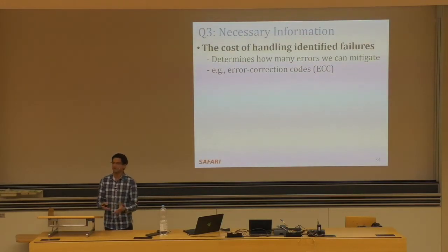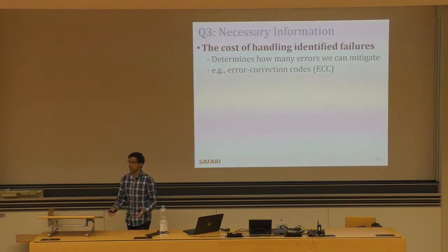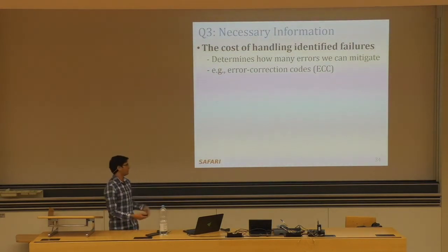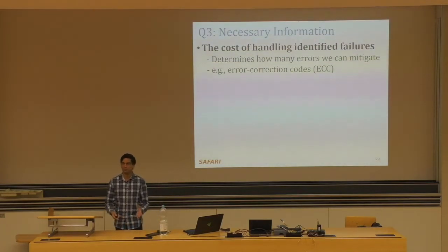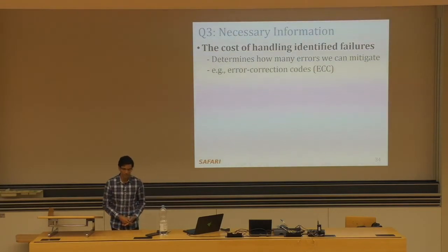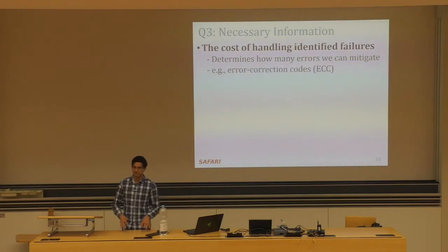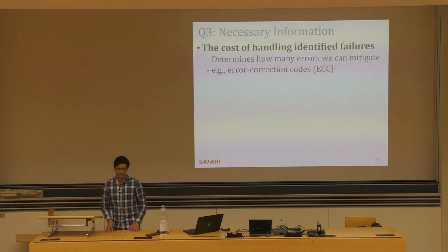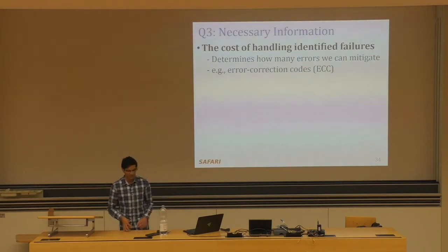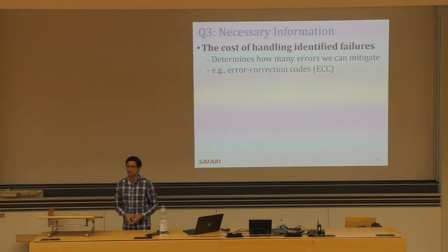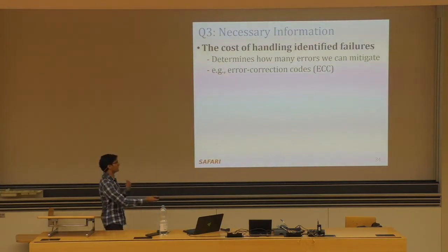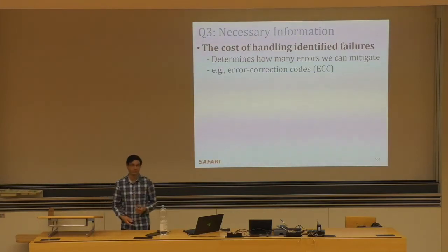However, if we have two errors in the ECC word, it'll manifest as an uncorrectable error, and that'll be a big problem for us. On the other hand, there's many different papers that propose fancier mechanisms. For example, there's a paper called REAPER, which hopefully one of us will present later on during the semester. This paper proposes bucketing different regions of DRAM into different buckets that can be refreshed at different refresh rates. And so all you're doing by having false positives is just moving regions of DRAM from one bucket into another. And if you're not doing too much of that, maybe it's not a big deal at all, right? And so knowing the error mitigation mechanism, we can sort of identify the cost of handling those errors.